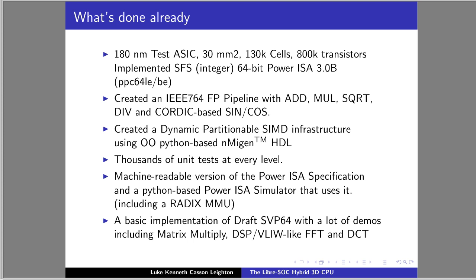So if you have 128 registers, you could probably get away with doing a 32-wide FP64 FFT and a 32-wide DCT, because you have to have the full coefficient set in memory for the DCT. I won't go into details. There's a heck of a lot behind that.